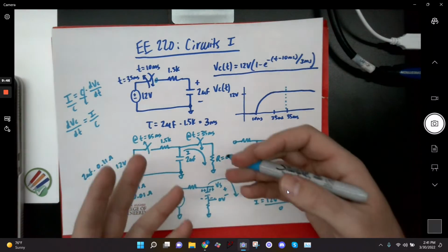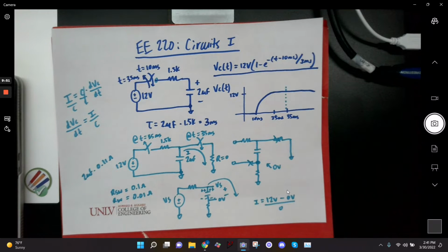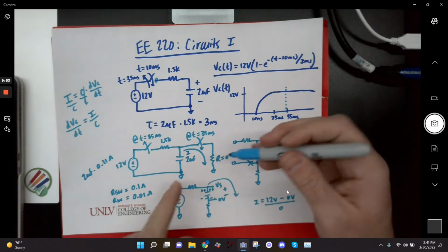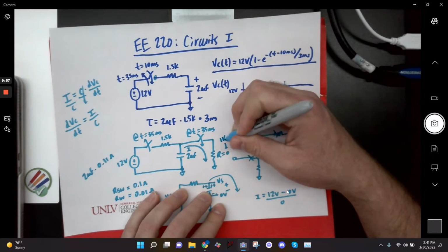In an ideal circuit, though, like LTSpice, where everything has 0 resistance, you will get infinite current, and it can cause some simulation problems. So you want to discharge through a known resistance. Does that make sense? Like maybe 1K or something.